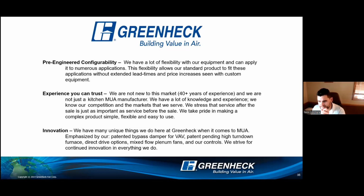And lastly, innovation. We have many unique things we do here at Greenheck when it comes to makeup air, emphasizing our patented bypass damper and variable volume, which I mentioned, and the high turn down furnace, direct drive options, mixed flow plenum fans, and our controls. The key detail here: every single one of our makeup air units under 25,000 CFM is direct drive plenum. What does that mean? VFD. So every unit has a VFD in it.